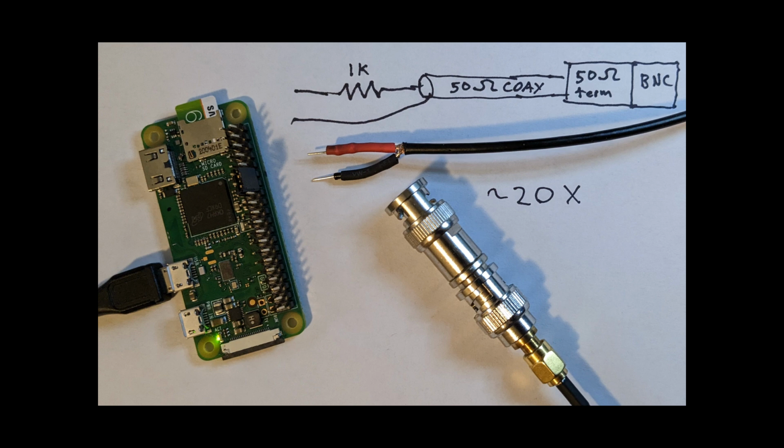What we have here is a piece of coax, a 50 ohm coax, and on one end I've soldered a 1K resistor, and on the other end and next to it there's a ground lead, just the braided shield of the cable. And this probe has to be used with a 50 ohm termination on the oscilloscope. So there's also shown on the other end of the cable both its BNC connection and a 50 ohm through terminator. And so the problem with this method is that it loads the circuit down more. And that's a concern, especially with the Raspberry Pi set to drive at its minimum strength.